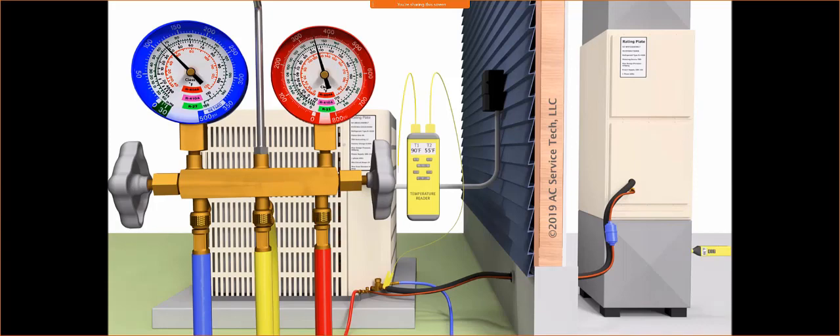All right, delta T is actually the temperature difference between 2 points. So we have our furnace over here. Our incoming air will come up from the bottom, going upwards, and we'll have, let's just say, 70 degrees. That 70 degree air comes up through the evaporator, and eventually comes out through the top. What we should see is about a 20 degree difference. So the air leaving the evaporator is going to be 50 degrees. That's what they mean by delta T.